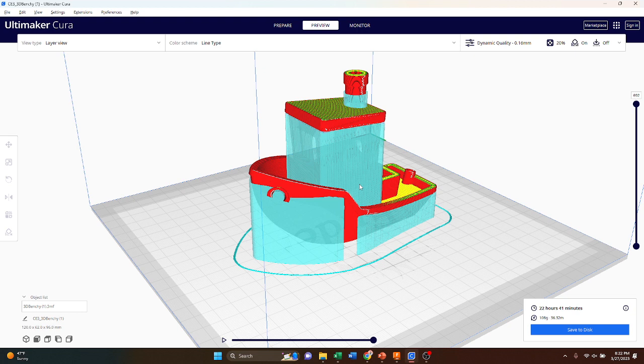So it's not crucial, not the end of the world, but just take that lightly into consideration whenever you go to design your final project. Don't make things that would be impossible to print, again, by just having super long overhangs, as you saw earlier.